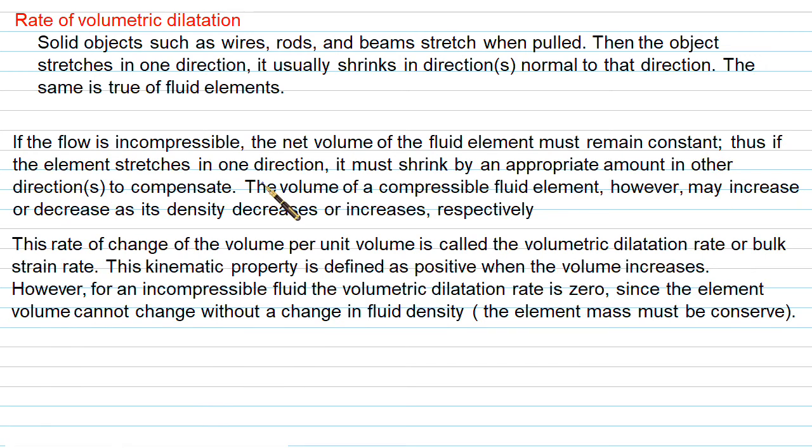Now we have introduced here the strain rate along the x direction, y direction and z direction, that is given as epsilon dot x as del u by del x, epsilon dot y as del v by del y, and epsilon dot z as del w by del z. Now we'll consider here a rate of volumetric dilation.